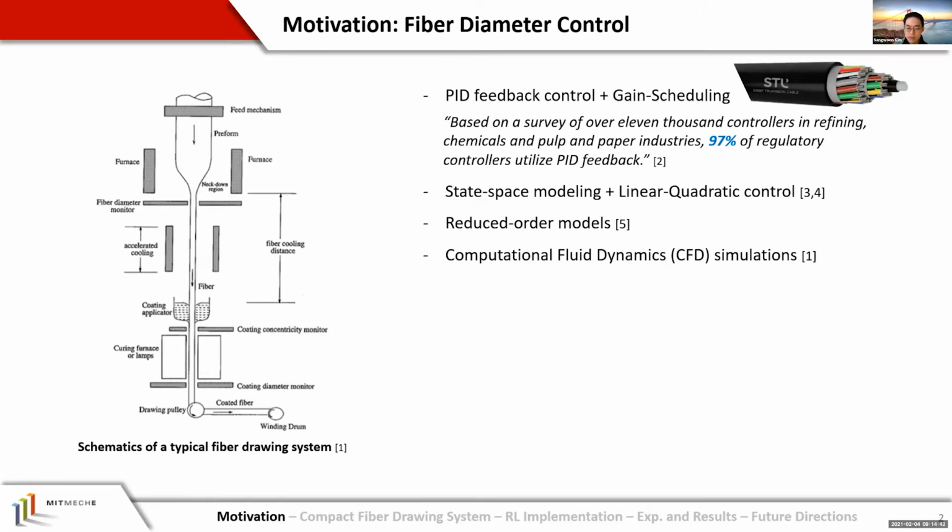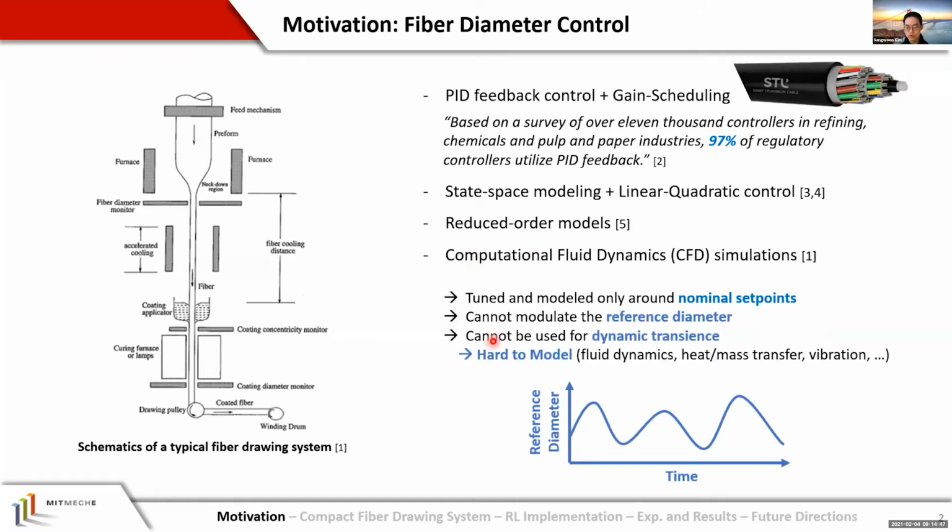However, there are several limitations to these approaches. One limitation is that the controllers are tuned and modeled only around the nominal set points. In other words, the controllers are only valid around those nominal set points. Therefore, they cannot be used when we try to modulate our reference trajectory or when we try to change our set point from one to another.